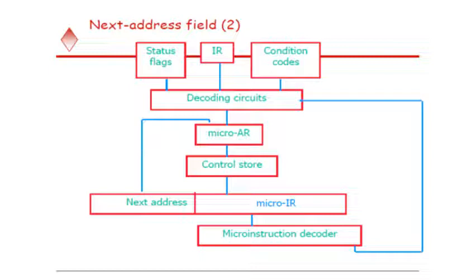Since each instruction contains the address of the next instruction, there is no need for a counter to keep track of sequential addresses. Hence, the microprogram counter is replaced with a microinstruction address register (MUAR), which is shown here.